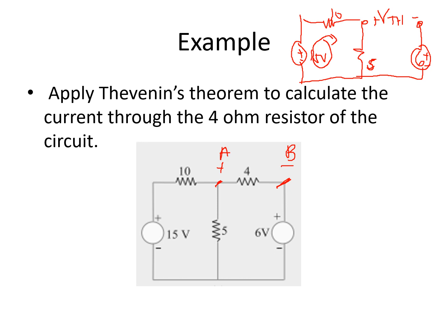So this 15 volts here will divide between 10 and 5. To know the voltage across 5 ohms, using voltage divider, this is simply 15 multiplied by 5 divided by 10 plus 5. So this is equivalent to 5 volts. Okay, so we now know that at this portion, we have positive, negative 5 volts.